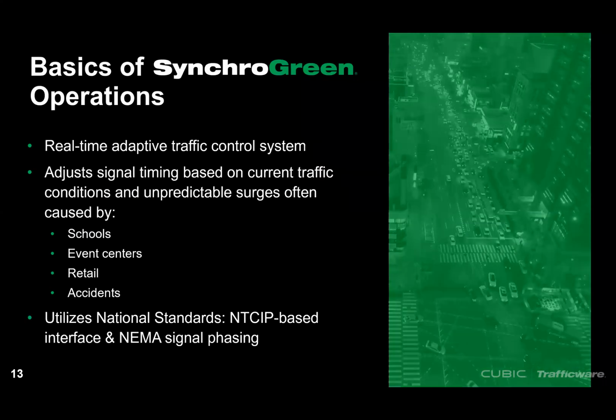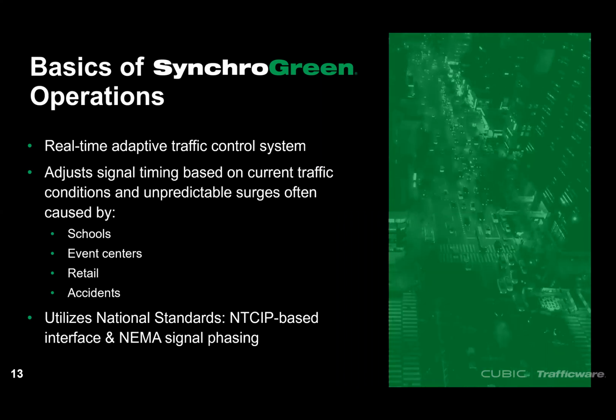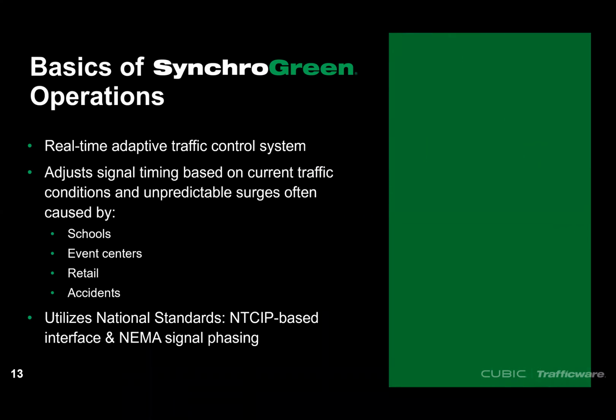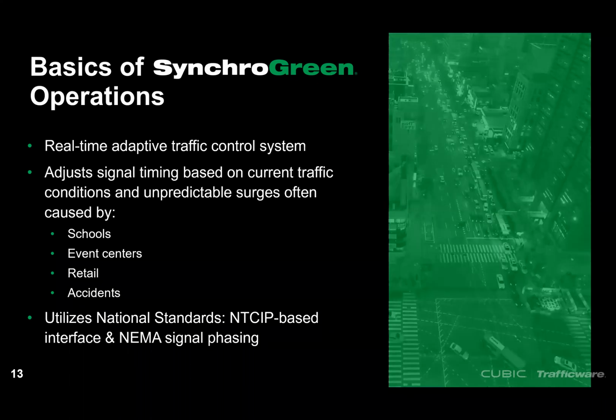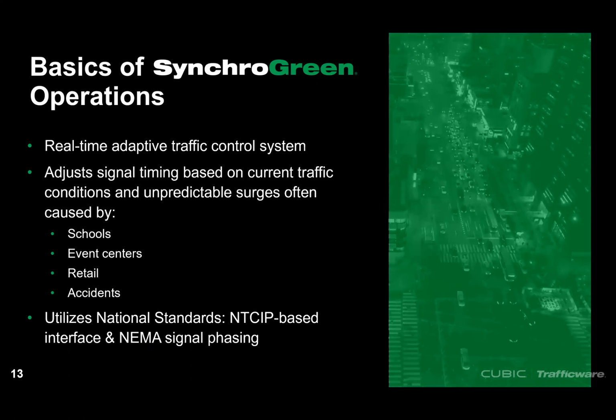So what are some of the basics of SynchroGreen operation? SynchroGreen is a real-time adaptive control system, meaning we're taking the detector information in real time from the field, and we're adjusting the signal timing on a cycle-by-cycle basis.